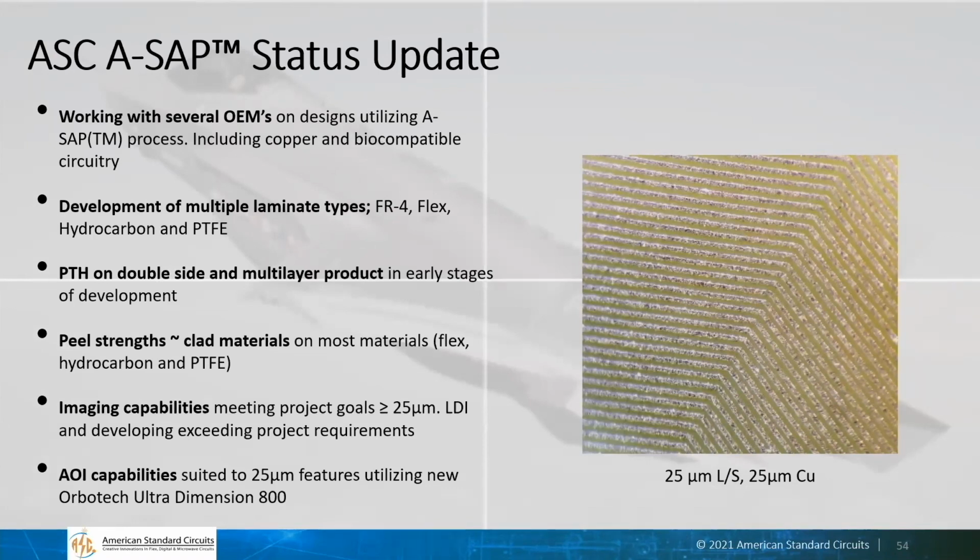Haris, and we are in the process of evaluating several other materials. I'm not certain if we'd call them the older traditional high PTFE type products. I believe the gentleman may be referring to something like 5880 or a GX GT type material, something in the 90 something range to 70% range PTFE. We can certainly include those types of materials to get data. Traditionally, they've used fairly aggressive tooth structure, so hopefully we wouldn't have any issues with coating and adhering to those substrates. But again, it remains to be seen.